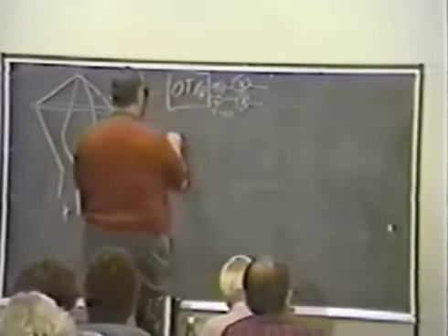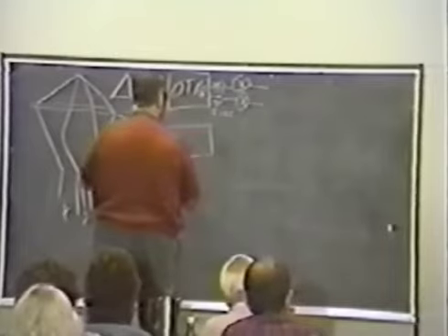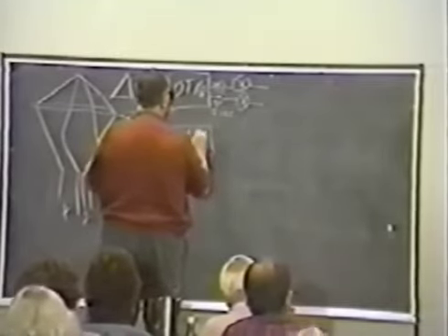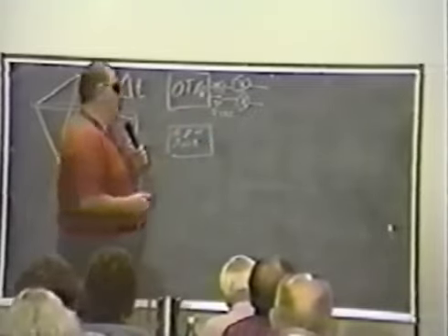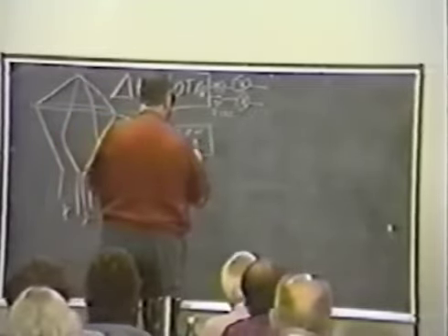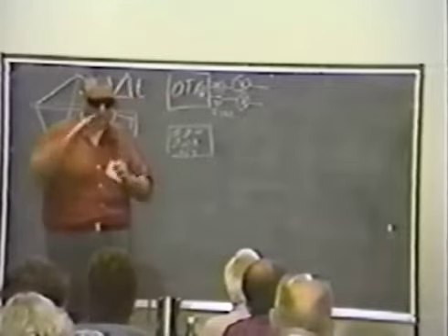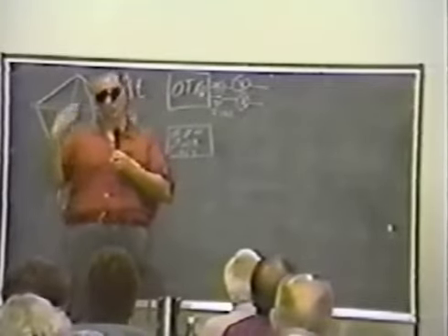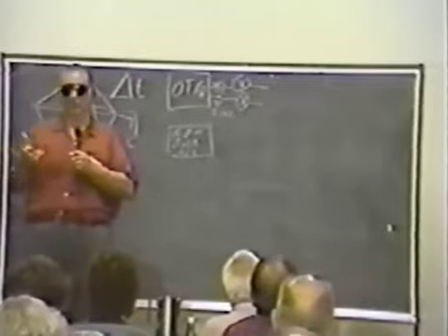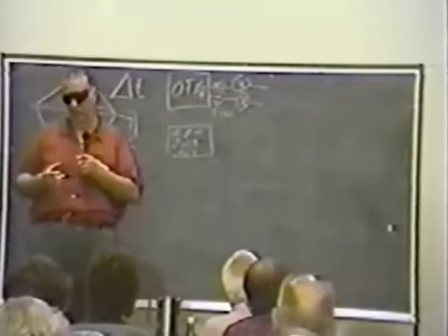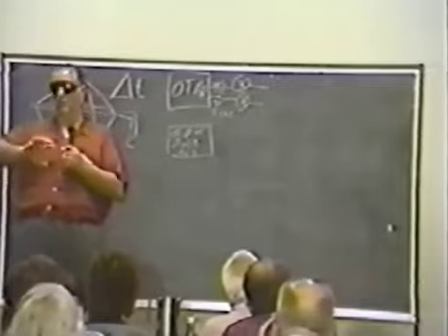Now, we take our white noise generator, our General Radio. I think it's an 1863, if I recall, which is a little box about that big that has a Gaussian noise tube in it and 2 6AQ5 amplifiers with its levels and a level control meter for its output, has bandwidth limitations.